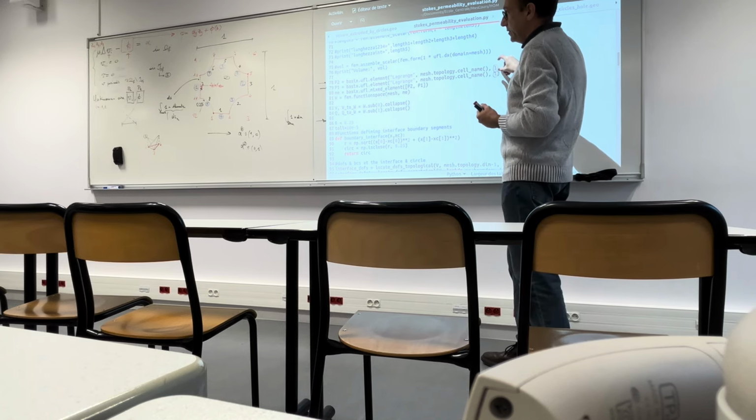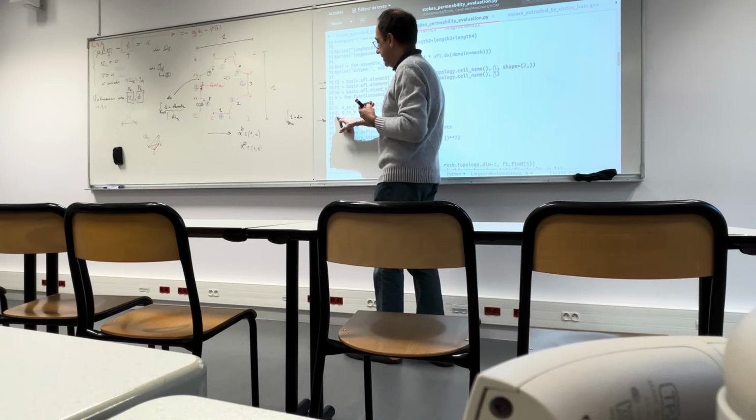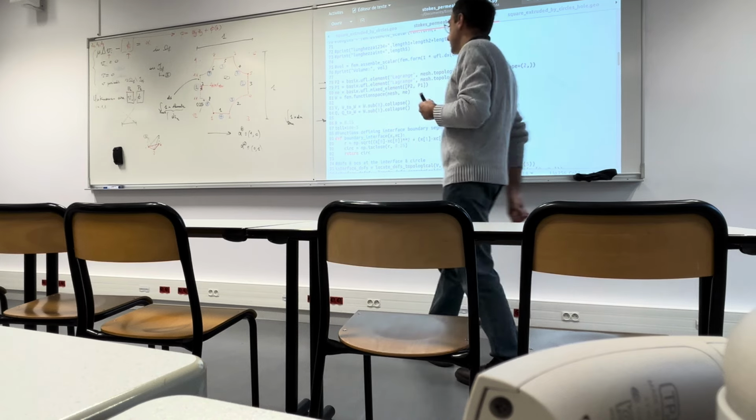Then we have constructed this mixed element for the list of unknowns, which are V1, V2, and Phi, and then the space W where we look for the solution. And then we decompose this W into V and Q, the subspace of W relative to velocity, the subspace of W relative to pressure solution. Okay?